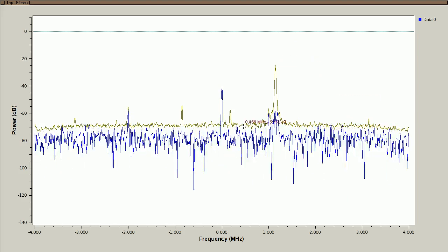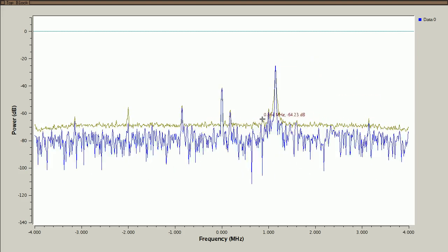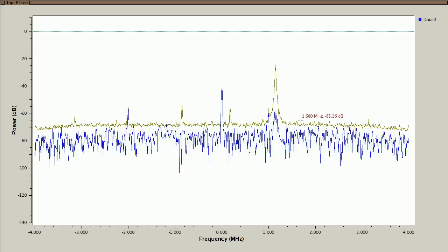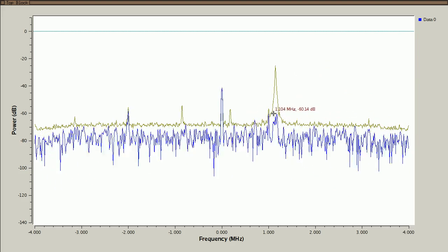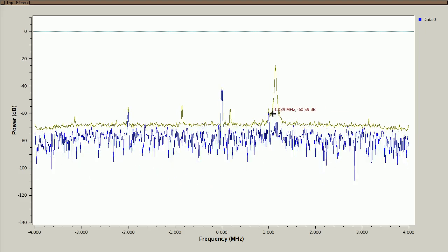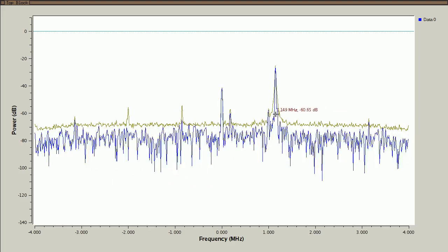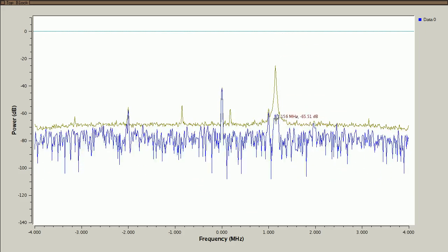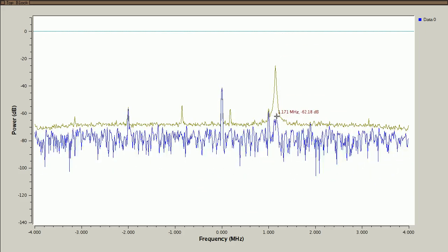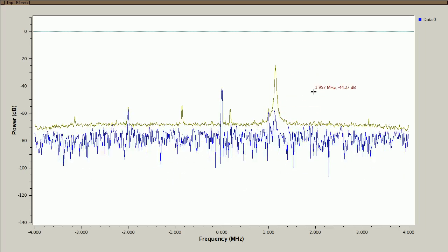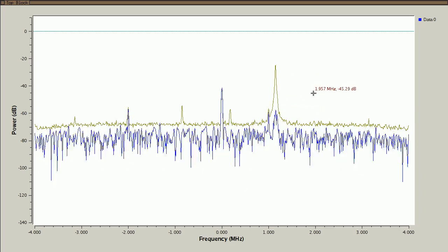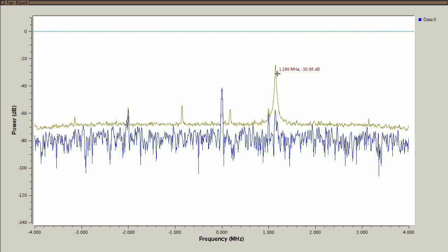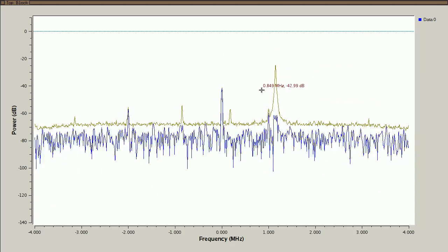And we're not transmitting that broadband noise anymore over 2 megahertz of bandwidth, although we are transmitting broadband noise over this 100 kilohertz of bandwidth right here. Even between bursts, between the intentional bursts, we are transmitting a little bit of noise. So we're definitely being a much better neighbor on the spectrum than we were, although it looks like there may be some ways that we could still be a better neighbor on the spectrum yet.